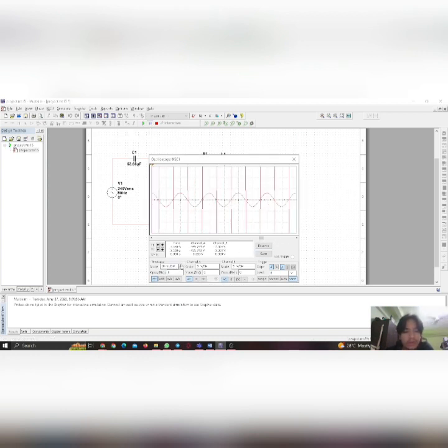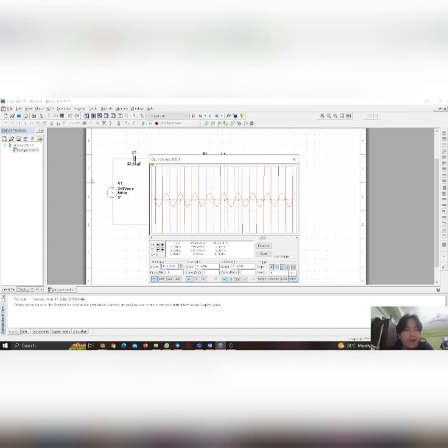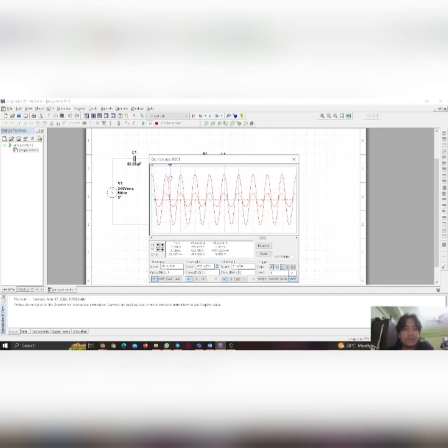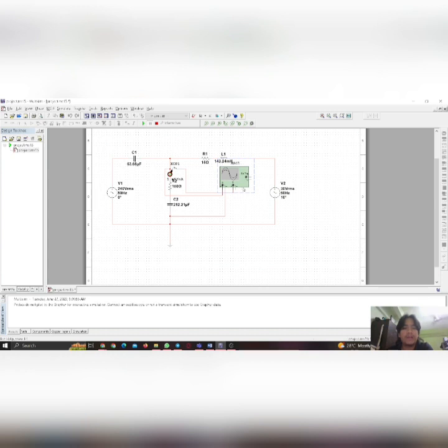For the scale, we use 20 milliseconds because we use 50 Hz. Channel A is voltage. This is T2, so we can get the VP, which is 455.749 volts, and our peak current waveform is 3.013 ampere.